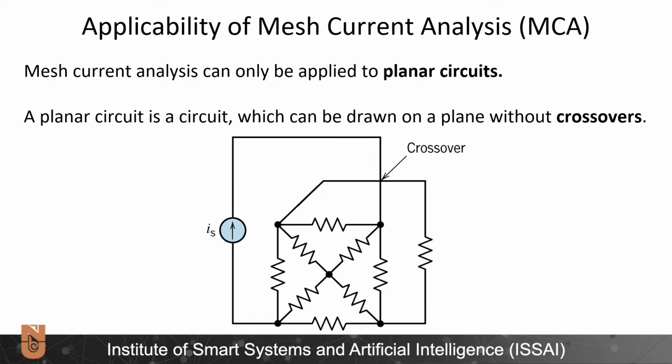Mesh current analysis can only be applied to planar circuits. A planar circuit is a circuit which can be drawn on a plane without crossovers. For instance, this circuit here is not a planar circuit because we have one crossover here.